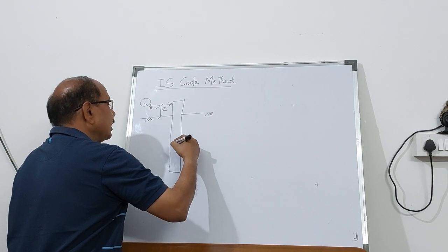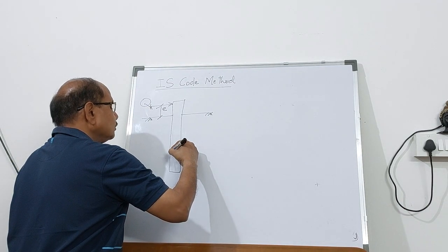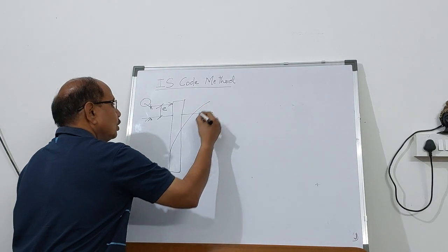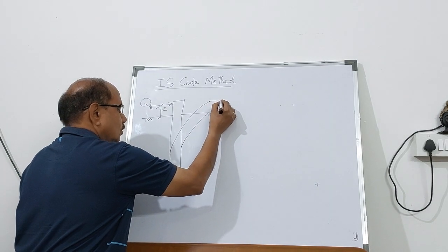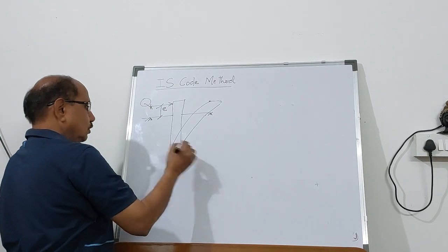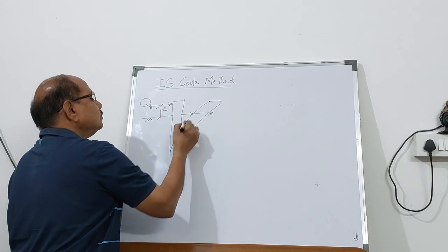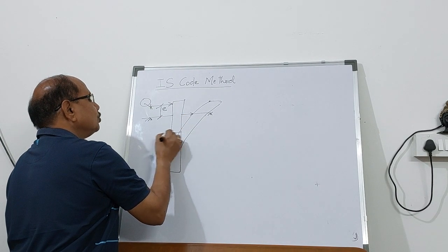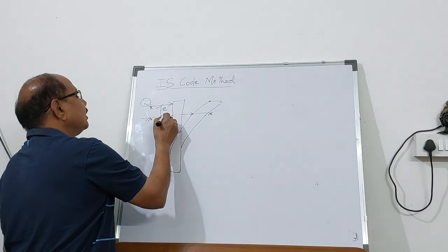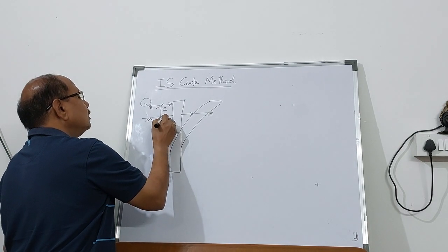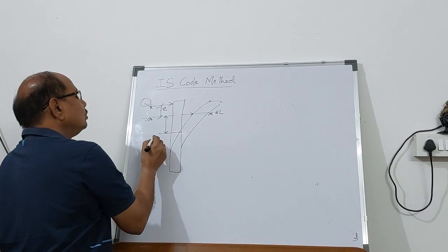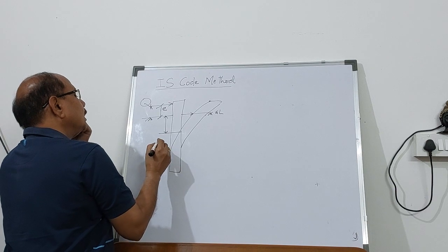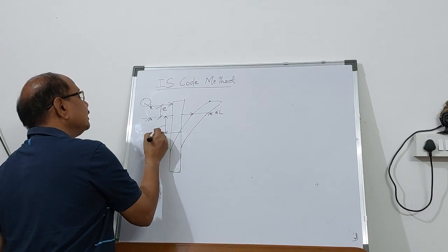This pile is a free-headed pile, and you know the deflection. So the deflection will be 0 at a certain depth. So deflection is practically 0 at a certain depth, and from the ground level to where the deflection is 0, it is called the depth of fixity.